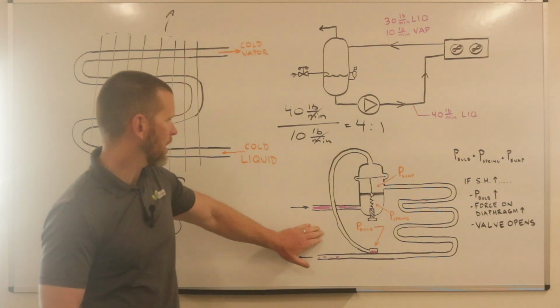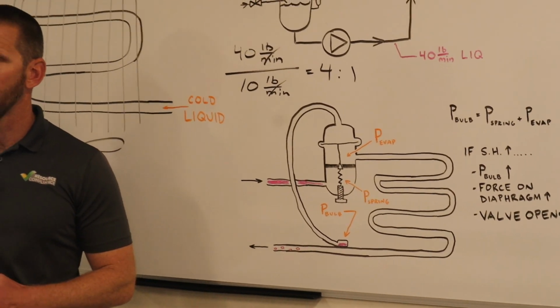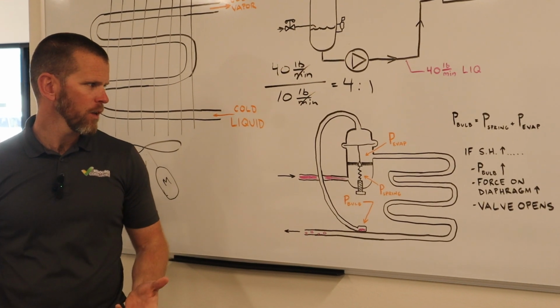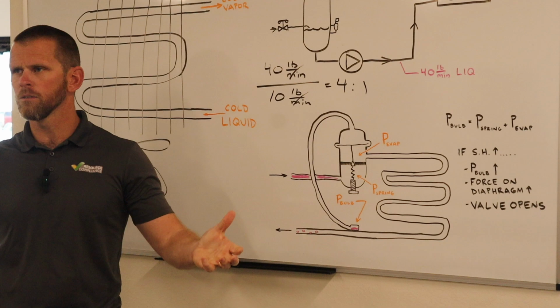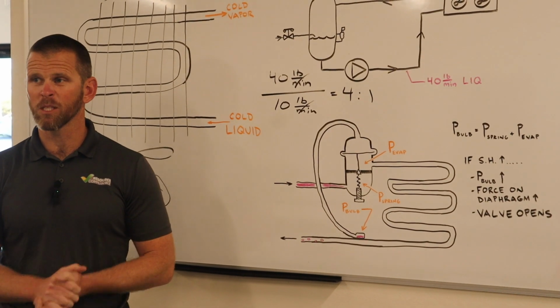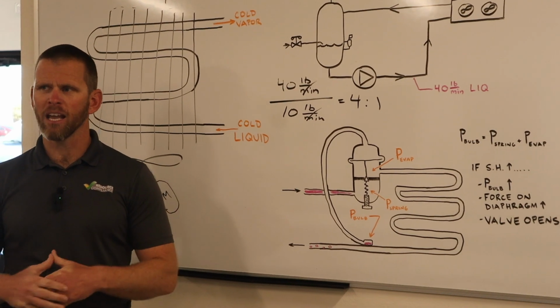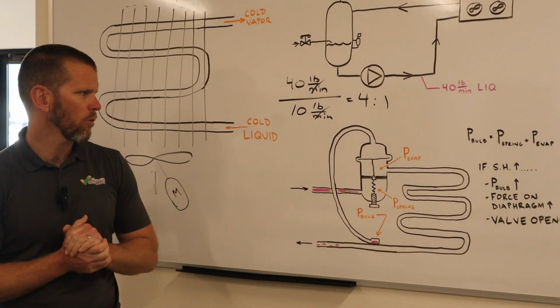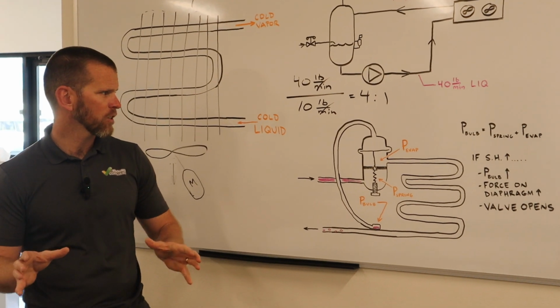All right, what I've got drawn here on the whiteboard is a cutaway of a thermostatic expansion valve, often called a TXV, okay? And this is a type of expansion valve widely used in refrigeration systems, especially historically, but also in a lot of higher temperature applications, commercial systems, and so forth. And so first, just a little bit of naming conventions, what things are called.